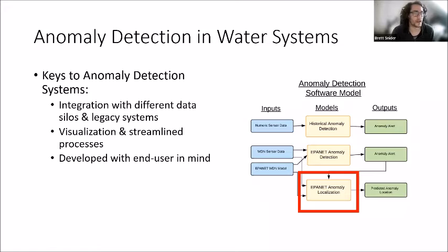So as the digital transition of water systems continues, one key thing that's probably going to happen for most systems is the implementation of remote sensors. And these remote sensors are going to become more and more common, and handling the data generated by these sensors is going to be very difficult for many of these utilities. It's impractical for water utility operators to analyze the data generated by these sensors as it's produced. Therefore, tools are going to be needed that can analyze this data and detect anomalies within the data, and then use that information to notify the staff of a possible issue.